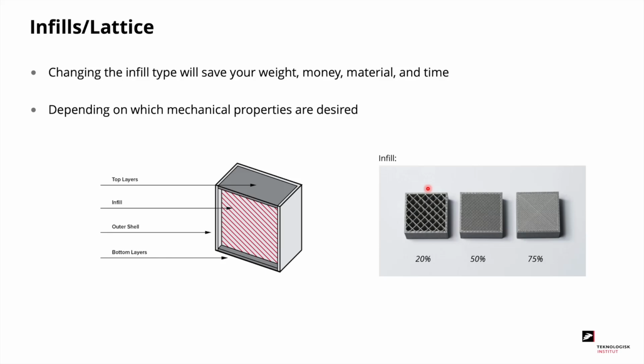Having a less dense part will save you weight and money and material and print time. But you should be aware that when using infill, you will change the mechanical properties of the part. And if you have a low infill, you will also have a weaker part.